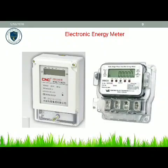In digital meter, power is directly measured by a high-end processor. The power is integrated by logic circuits to get the energy, and also, for testing and calibration purposes, it is then converted to frequency or pulse rate.